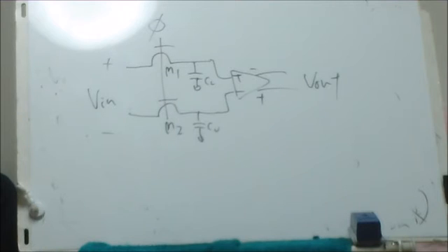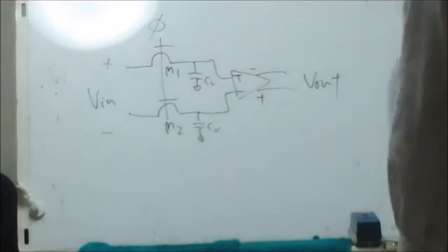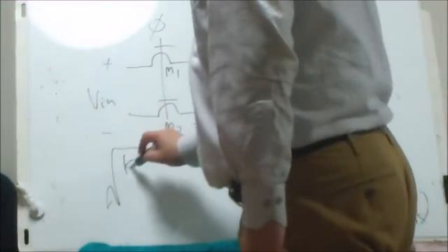If we think of the MOSFET in figure 7 as a resistor, then we can add this RMS noise source and feed with the output capacitor. The noise can be regarded as a sampled voltage onto the capacitor each time the switch is turned on. Square root kT over C noise.